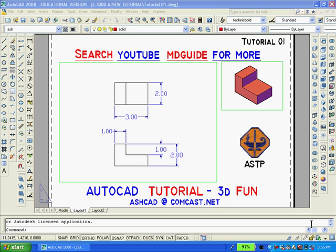And you can tell by the UCS icon in the lower left corner that we are now in paper space. With the erase command, I'm going to remove or erase the two viewports.